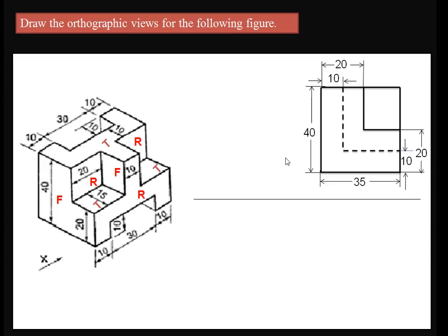Now from this front view we can project the top view by drawing the construction lines from each and every side or edge of the front view. Draw the projection lines or construction lines like this. After this I want to analyze the shape again. In the top view, whatever the T letter I have represented, those surfaces we can see, and when you join all the surfaces we can see a particular shape. Initially, in the top view, assume this edge as a straight line.